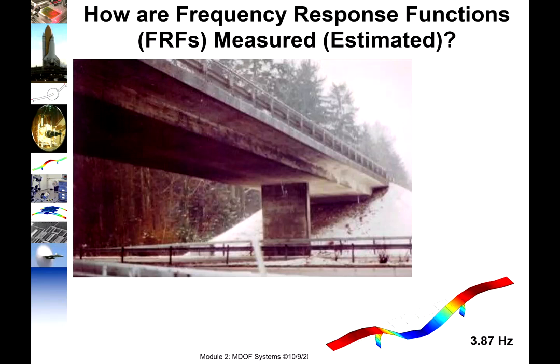Our last few lectures have talked about how we use FFTs in frequency response to solve vibration problems. So given the force and knowing something about the properties of the system, how do we calculate the response? Today we're going to flip that around and talk about how we can take a structure such as this bridge here, and take measurements, apply forces, and measure responses to figure out what the system is that made that response. So usually our goal is to figure out what the modes of vibration are, what the natural frequencies and damping and mode shapes are.